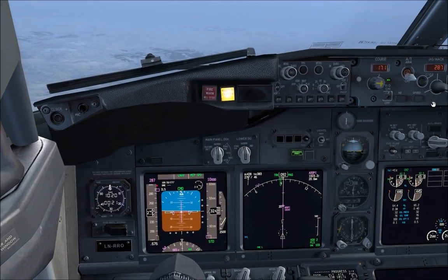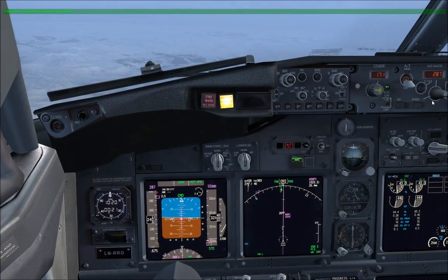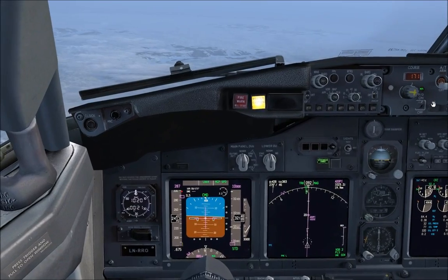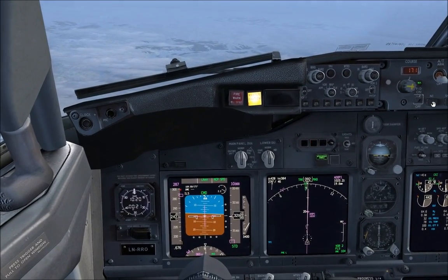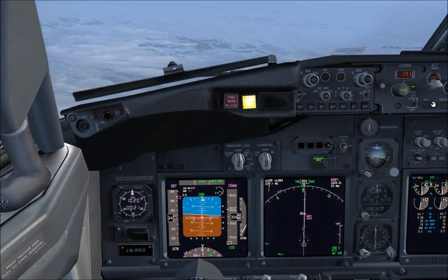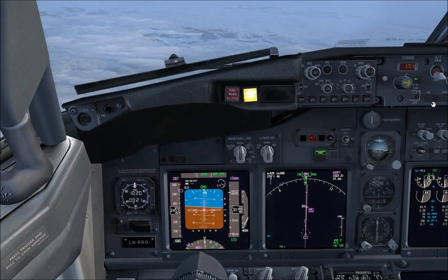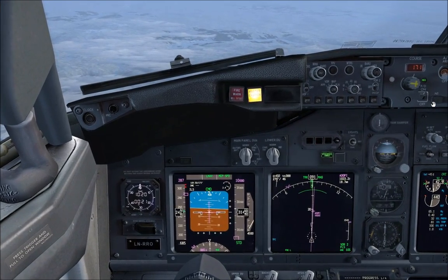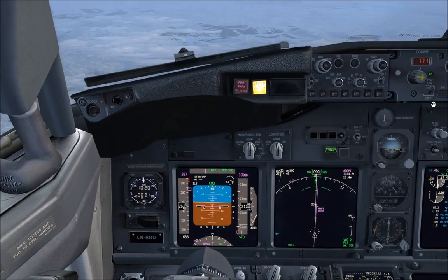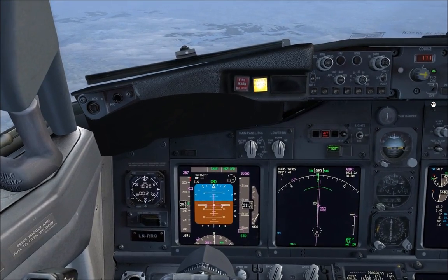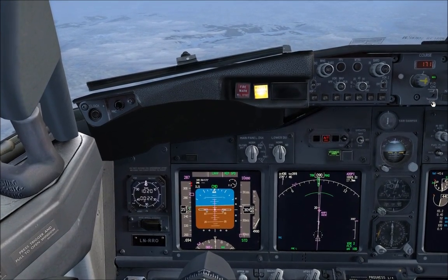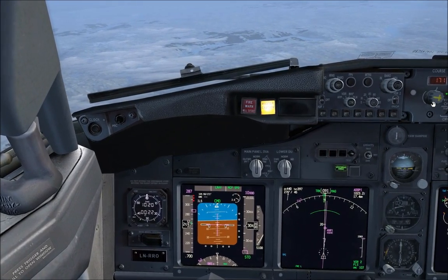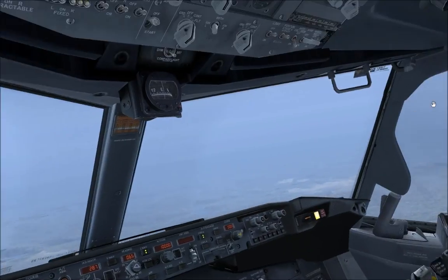Emergency descent checklist. Condition: one or more of these occur. Cabin altitude cannot be controlled when the airplane is above 14,000 feet. A rapid descent is needed. Memory items: announce the emergency descent. The captain will advise the cabin crew on the PA system of impending rapid descent. The first officer will advise ATC and obtain the area altimeter setting.